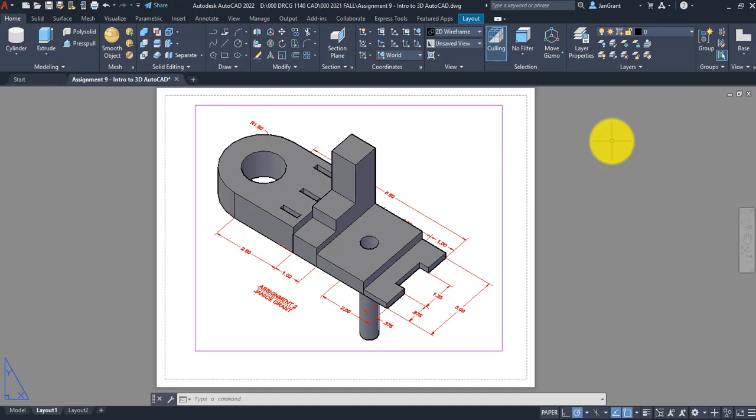switch it before you start putting your text, right? And in fact, since we already have dim text layer, you can use layer 0 if you want. I'm going to use layer 0.